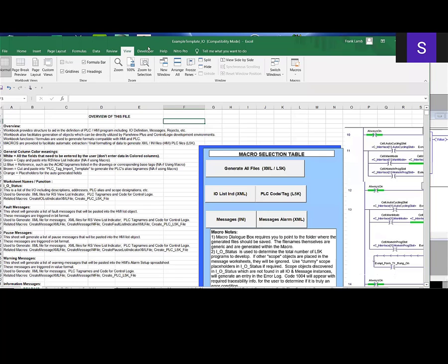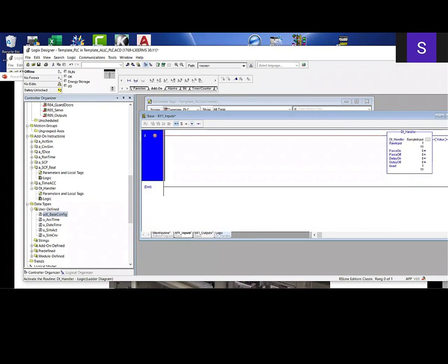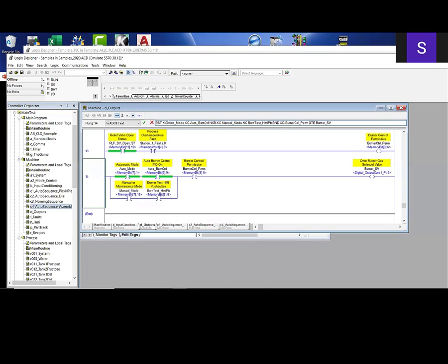So Allen Bradley, I'll go ahead and show you how Allen Bradley's text version of code looks. We'll do this here. But there is a text in any PLC program, doesn't matter what brand it is, there's always a text version of code. So this one here, you can see that's a picture, that's ladder logic, and it says burner, solenoid valve, auto mode, auto burn control. If I double click this wrong, I get this text right up here. This text is an ASCII version, and that's what Allen Bradley calls this, of this rung, right?